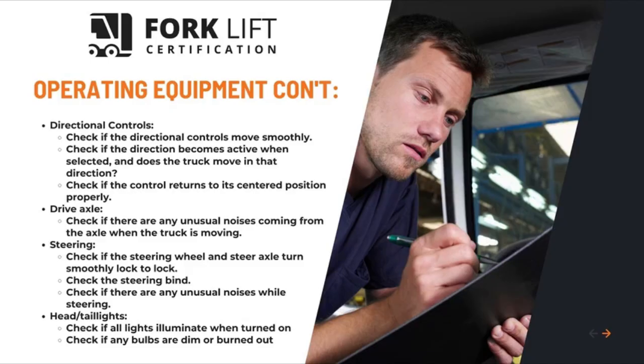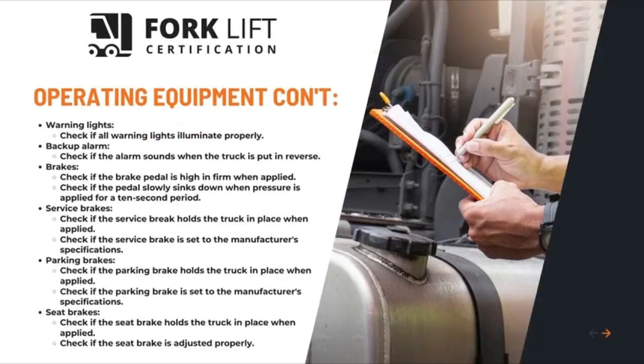Headlights and taillights. Check if all lights illuminate when turned on. Check if any bulbs are dim or burned out. Warning lights. Check if all warning lights illuminate properly. Backup alarm. Check if the alarm sounds when the truck is put in reverse.